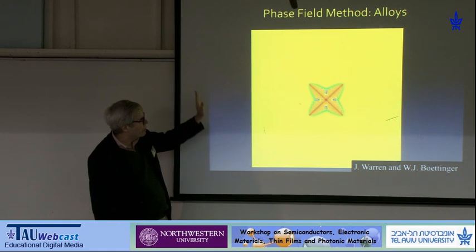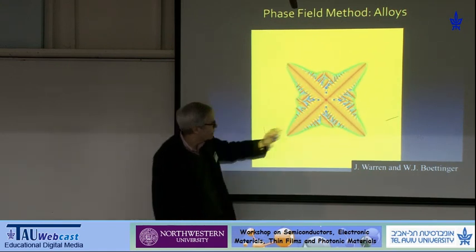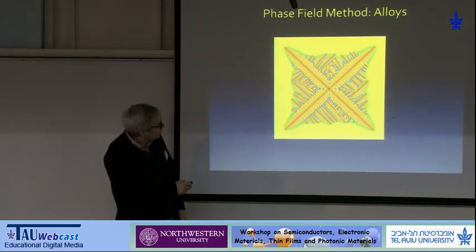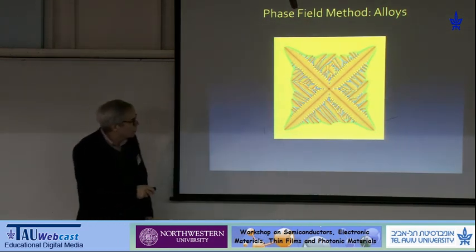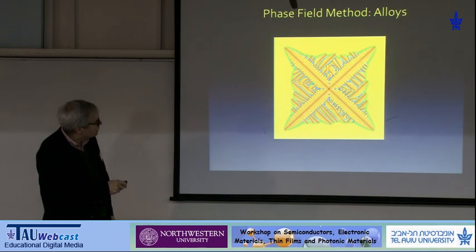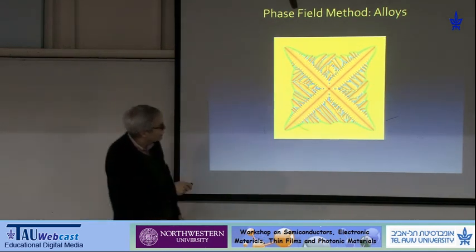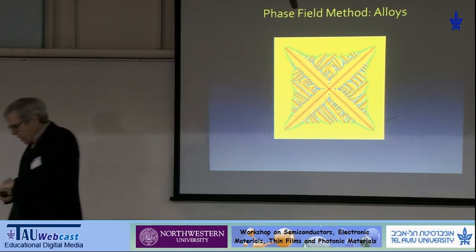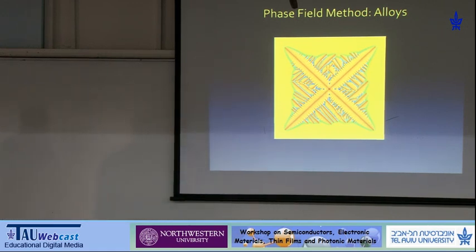If you look at any microstructure of a dendritic solidification process, you'd see precisely this. You'd see these stripes that go down the middle. It's called coring. You see all of this stuff that is segregated between these little secondary arms, exactly as you see. So it looks really good.